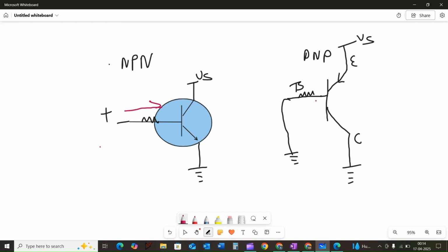the current flows out from the base terminal of the transistor. Remember that this is opposite to the direction of electron flow. The conventional current flows from higher to lower potential, whereas the electrons flow from low to high potential. Using conventional current simplifies analysis because the direction of the emitter arrow indicates the direction of emitter current.